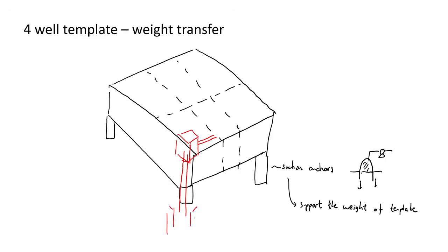The weight of the wellbore goes to the conductor. So these two are attached with this pipe, but they are not supported in the same way. It could be that due to thermal effects, for example when you're producing, the well heats up and starts to expand. So this is going to go up while the rest of the template stays in the same place. Then this piece of pipe is going to be subject to deformation and stress.